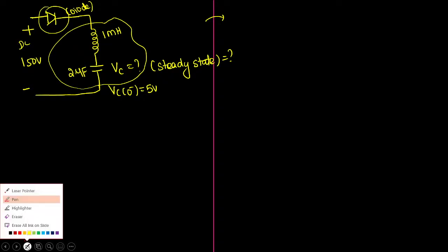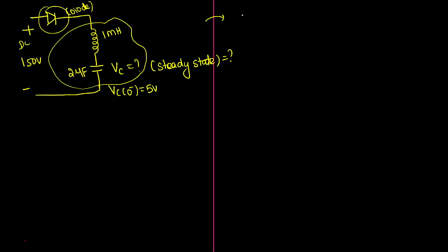Okay. Let me tell you. Basically, the generalized expression for the voltage for the LC circuit when it is connected with the DC supply can be written as, listen, supply voltage Vs into, in bracket, 1 minus cosine of omega t, plus the initial voltage across the capacitor, that is Vc0, into cos omega t. So here the voltage will become maximum, right?